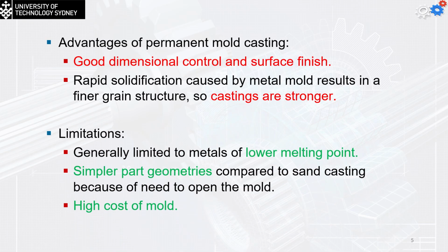The disadvantages or limitations are that it is generally limited to metals with lower melting points. The part geometry is simpler compared to castings made by sand casting, because of the need to open the mold instead of destroying it. Also, there is the high cost of the mold.